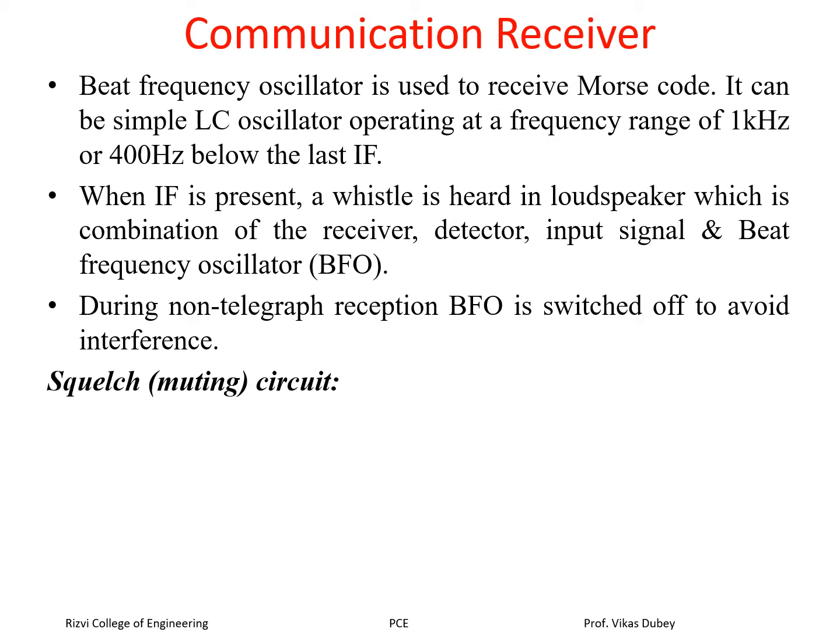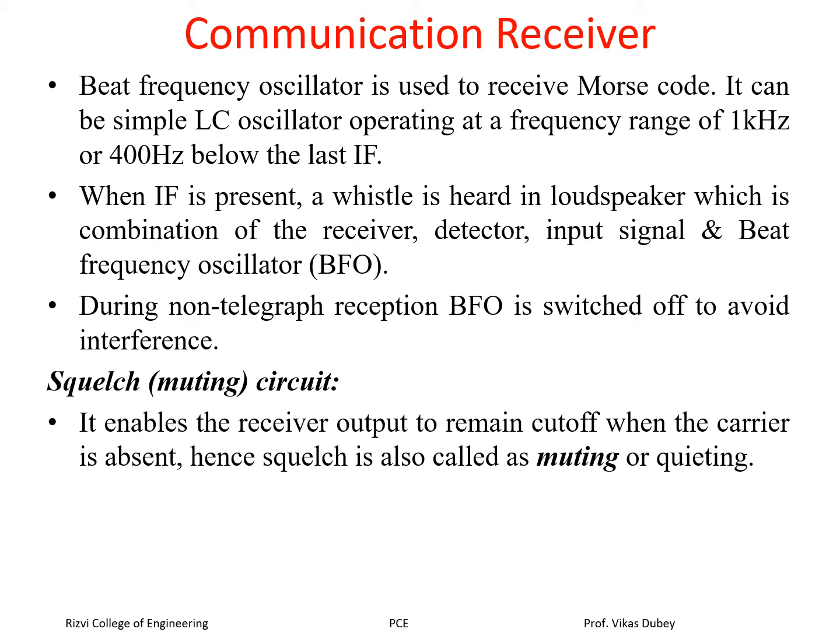Then the squelch circuit, also called a muting circuit. Why is it used? It keeps the receiver output cut off. It detaches the receiver when the carrier is absent. So when the carrier signal is absent, it cuts off the receiver. Hence, squelch is also called muting.